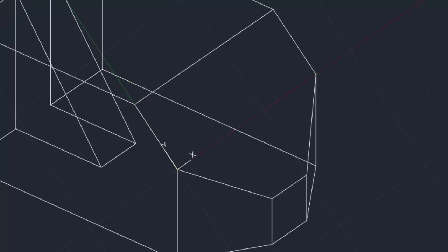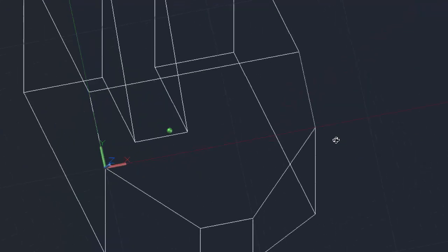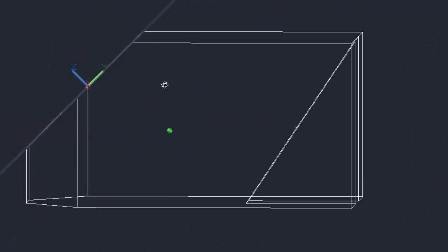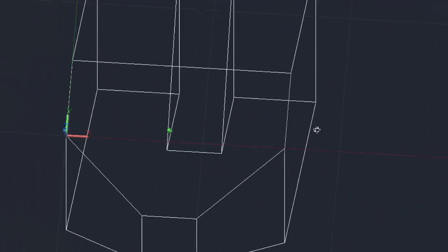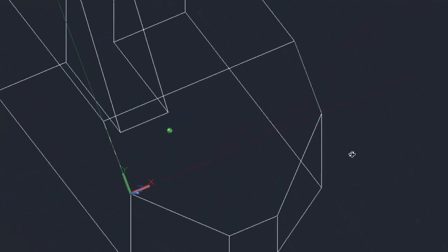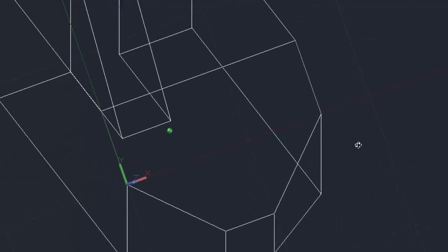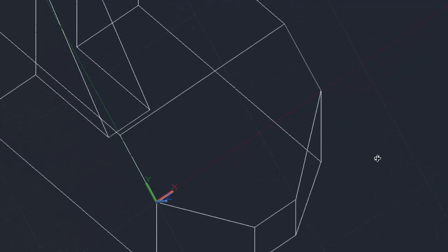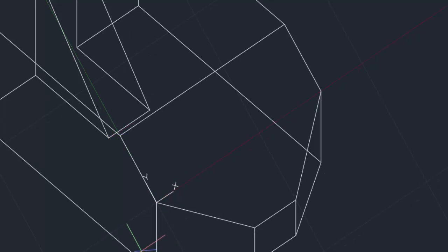Now, if I turn this around, you can see that I've got my drill possibilities dead right, but I'm going to have to go in the negative Z direction. Okay, but you can see I'm there, right? Now, that being the 0,0,0 point, to put a 1/4 inch drill hole on there, I just simply need to go back and get the circle command.